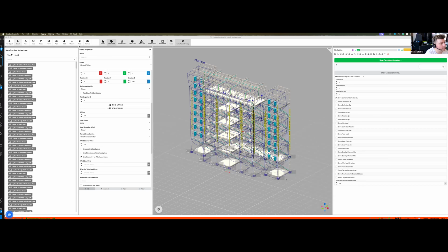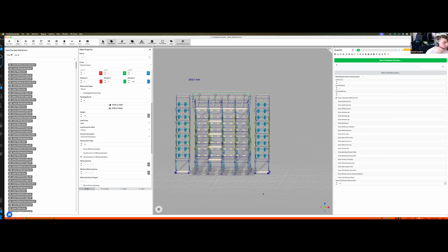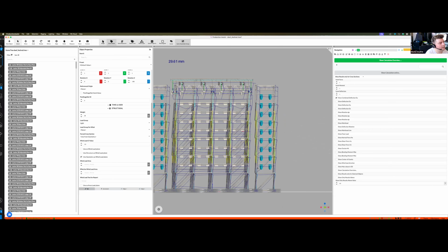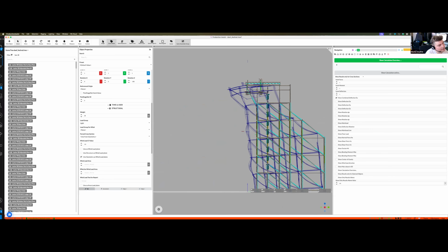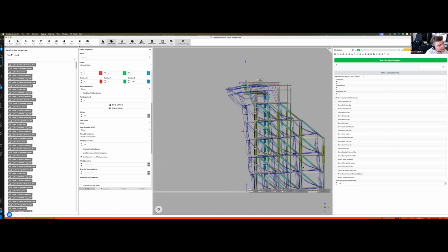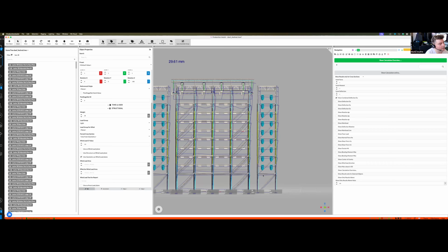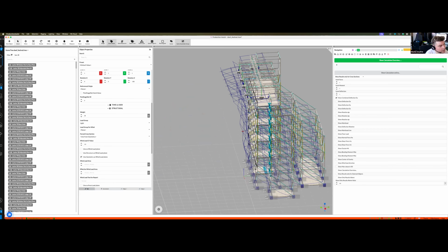So the wind load plane for this kind of fixtures is different when you look from here than when you look from the side. Every time, it's changing them and projecting them depending on the wind load angle, and it's doing this automatically. This works for all 3D geometries that can be imported into Production Assist.